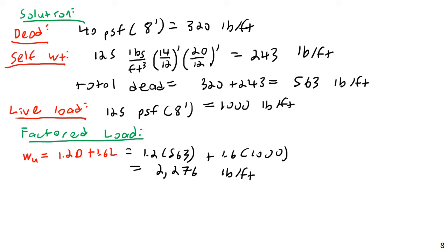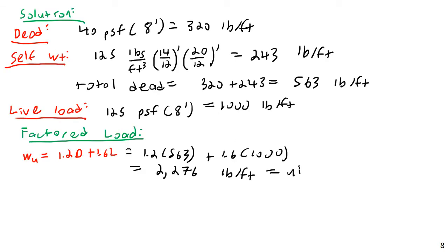And really all of this is leading up to a beam design example in case you can't figure that out. So we'll be looking at that going forward. Although today I don't think I'm going to work all the way through the beam design example. I just wanted to review a bit how to get your ultimate load for the sake of what we'll look at later. And we'll use this ultimate load in another lecture. Okay, so with that I would also like to actually calculate the ultimate moment. So I've got my ultimate load. So that's going to be my ultimate line load W.